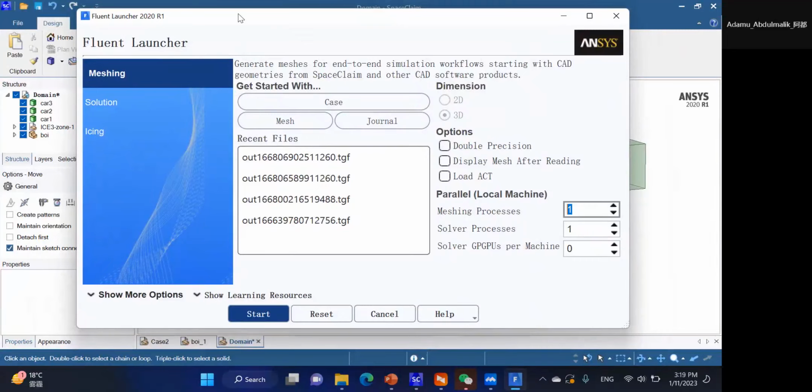The most coarse mesh is maybe around 10 million cells. In some studies, you see meshes of maybe 15 million, 20 million, even 50 million. If you want to study using large eddy simulation, which is a method, you're going to use at least 80 or 90 million cells, because you need smaller meshes to be able to compute the flow around the train.